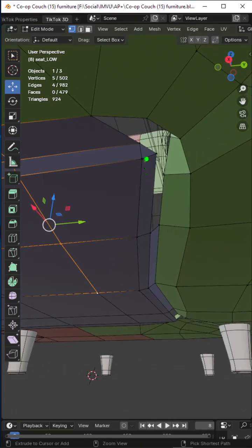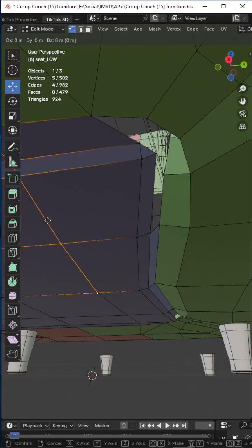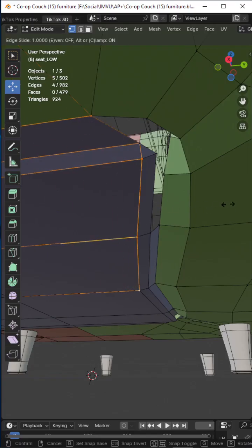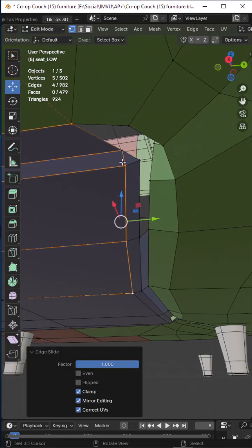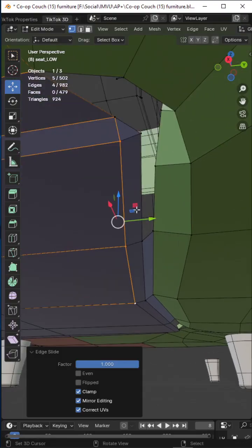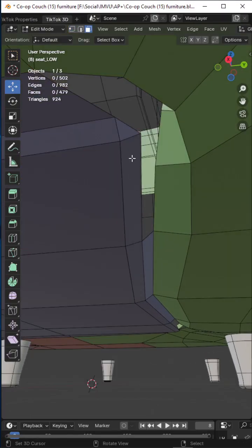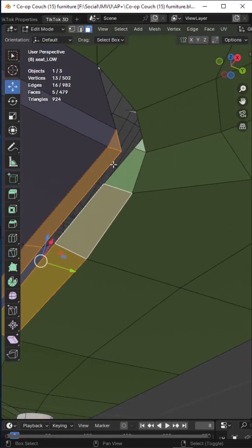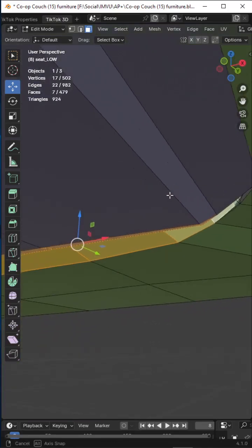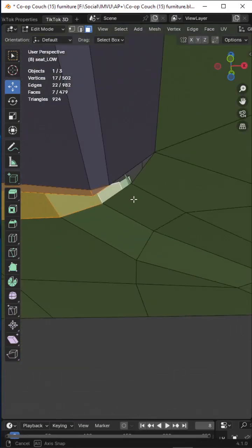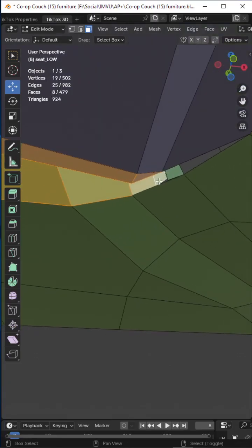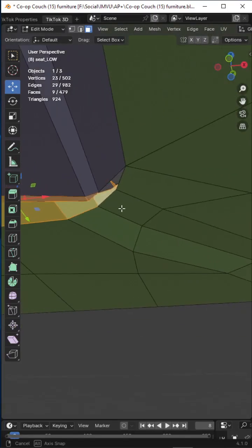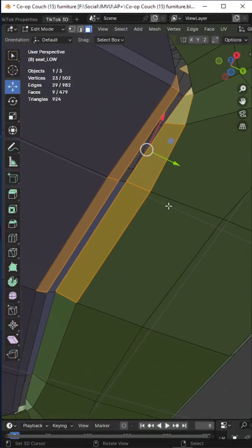So if we use this edge loop as our terminator, what that means is that we can then merge, double tap the G key, hold Control to snap to the grid, so that it snaps and locks to those vertices, because what we can then do is face select, just remove all of this, that goes inside the mesh, so get rid of that, delete.